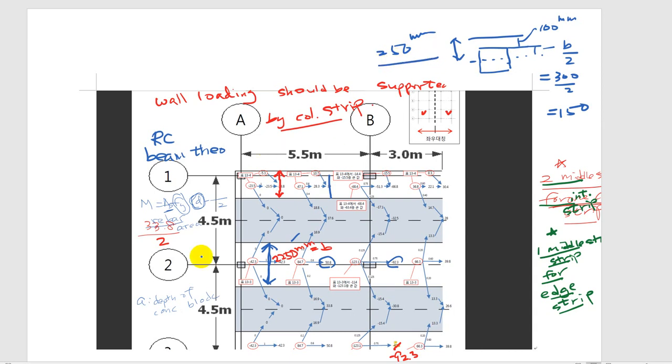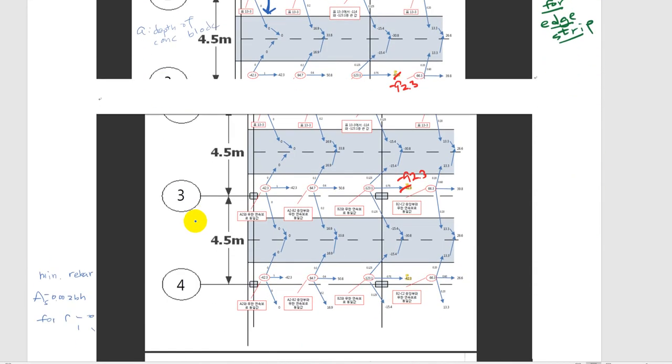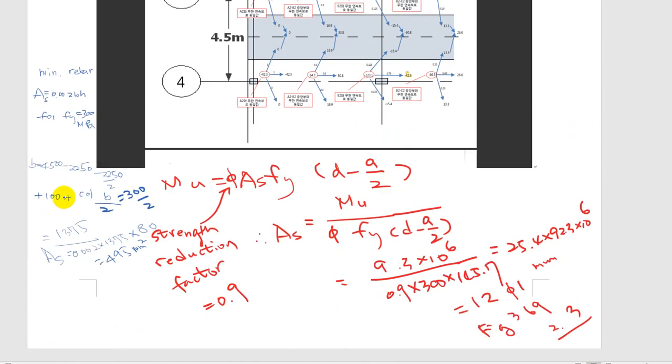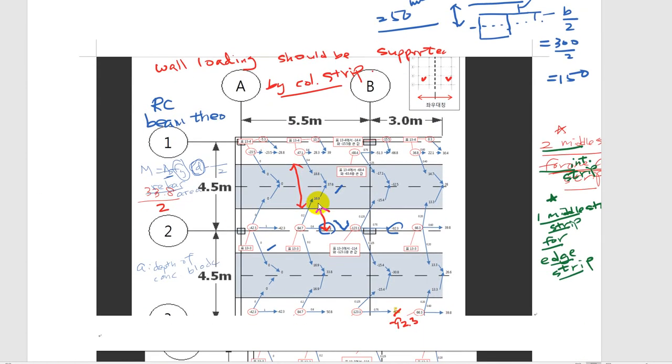So if you go back to this equation right here, you add this, which is 45. Then we have to subtract this and this from 4,500 in order to get the width of the edge slab. So my equation should go 4,500 minus this and minus this.